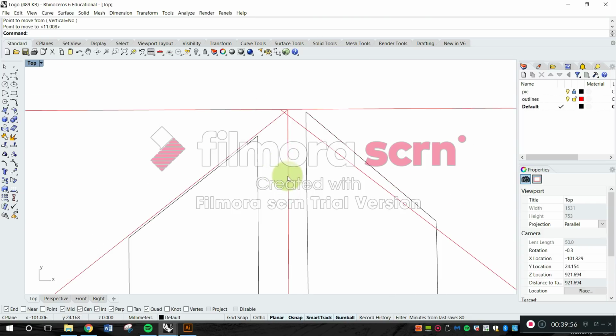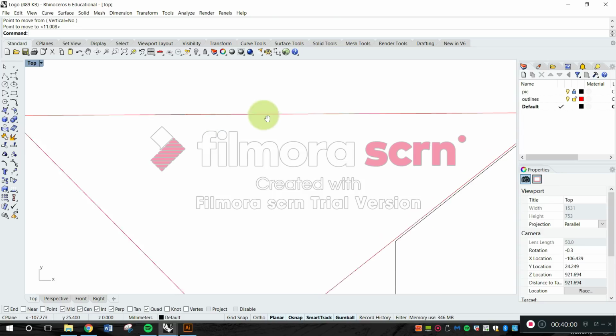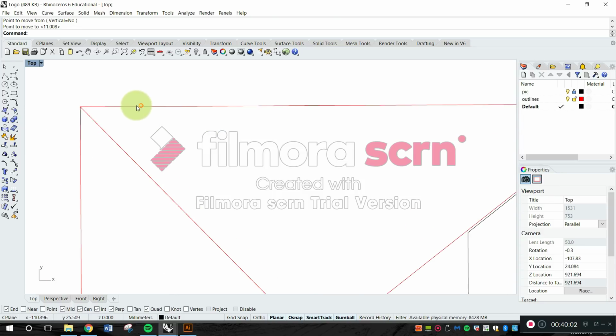You can see it better on your screen, but in Rhino, or actually even AutoCAD, this line right here looks kind of offset. It has little hairs, like little thicknesses. Thicker over here, thinner over here. That means that line is not parallel or orthogonal.